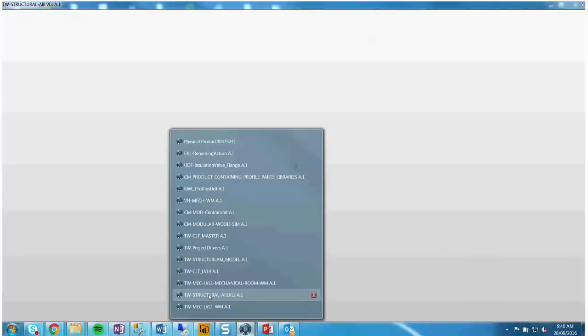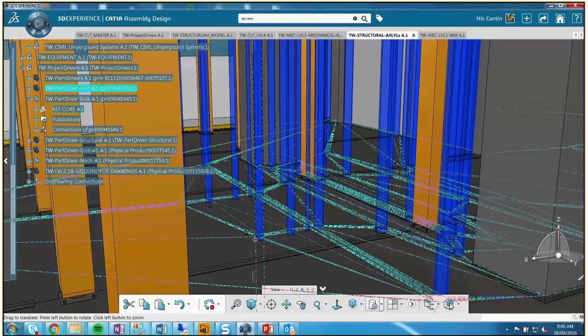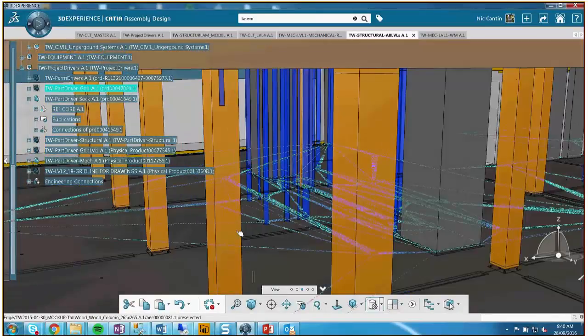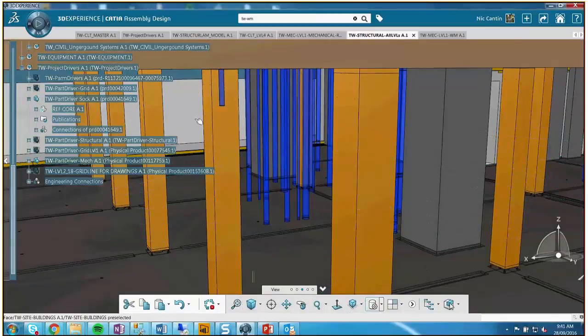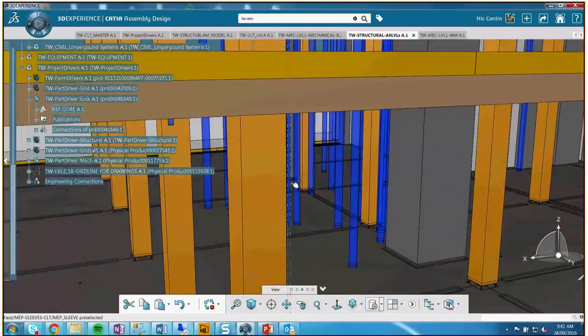How much repetition was there between the panels? There was quite a bit. I mean, 3 to 8 is typical, and then 9, there's the way they designed the risers, there's no penetrations at 9, so that was a different floor. And then the sizes from 9 to 17 were different in terms of the penetration, so they were slightly varying in that sense as well. But overall, I want to say 54 different panel types.